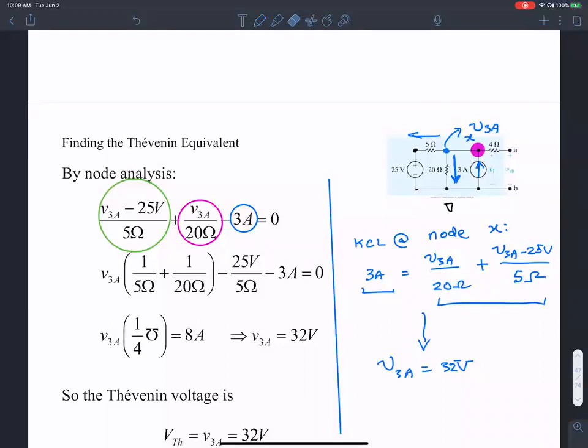Yeah. So the idea is this is at a positive potential, this is at a negative potential, right? Current flows from high potential to low potential. Arbitrarily, I chose the value to be this guy. So this is ground, assuming this to be ground. This voltage source, don't forget this guy, puts up a voltage of 25 over here. So this voltage minus this voltage is the voltage dropped across this resistance. Okay. Does that make sense? Yes. Okay, so that's the idea. The reason I chose negative 25 volts there is because of the voltage source here.